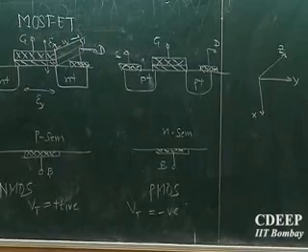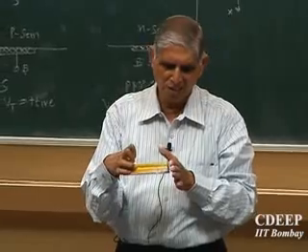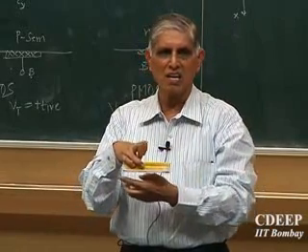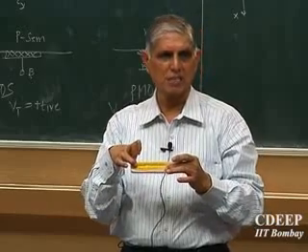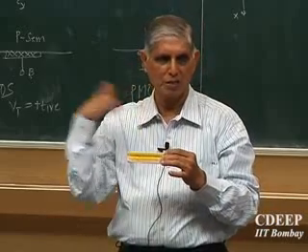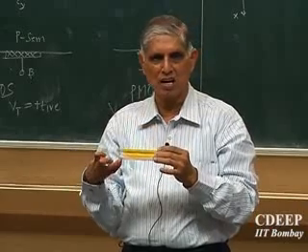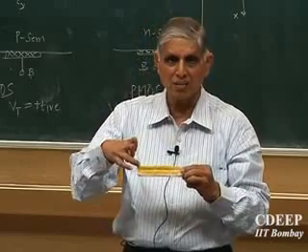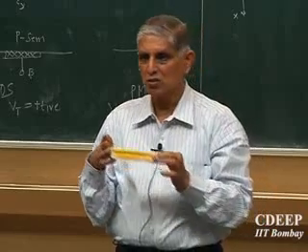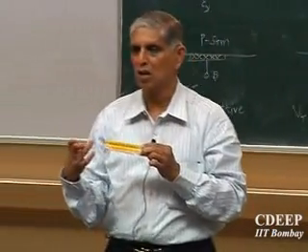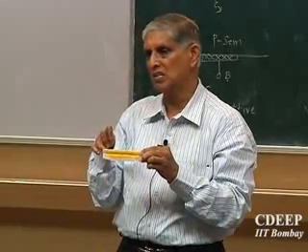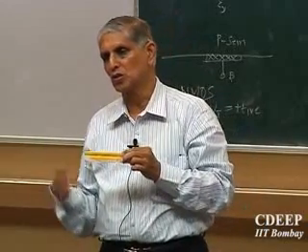So for example, let's take a duster. This side I cannot show you. On this side is the drain, this side is the source, this white part is the channel, the inversion layer, and the top yellow is the gate. If I apply an electric field or voltage here, I am creating electrons here. Let's say for NMOS, I apply positive VGS greater than VT, I create electrons. This is the channel length, and this is the channel width. Is that clear? So it's a three-dimensional device. Essentially the transport is along the Y direction, but controlled by the X direction. And how many carriers there are is decided by the Z direction, because this is the area or volume it's going to get to. Is that okay?